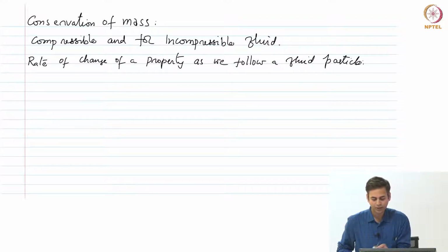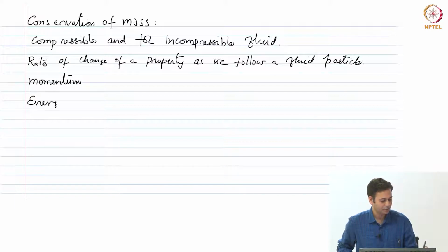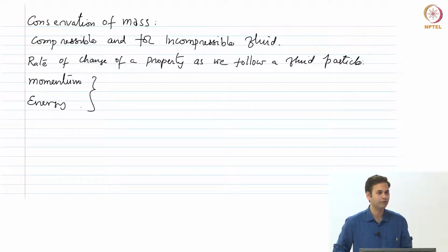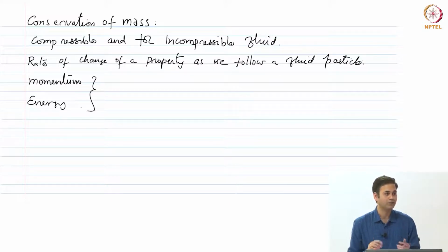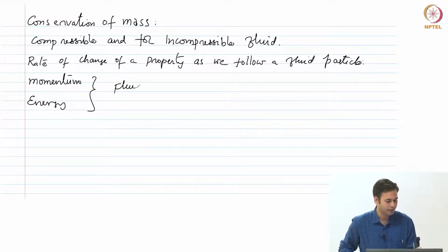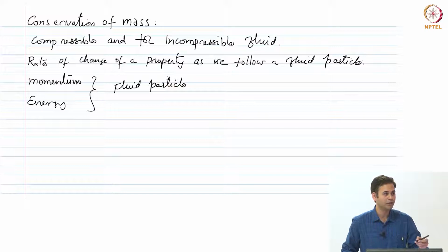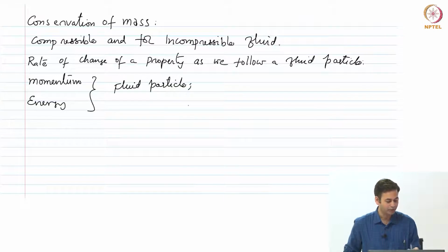The statements of conservation of momentum and energy are applied for a fluid particle or for a finite fluid element. For what are they applied? They are applied for a fluid particle, right? Newton's second law and the first law of thermodynamics are all applicable for a fluid particle or for a fluid of certain mass. We said the rate of change of momentum of a fluid particle equals the resultant forces acting on the fluid particle. So essentially we have to derive for a fluid particle.